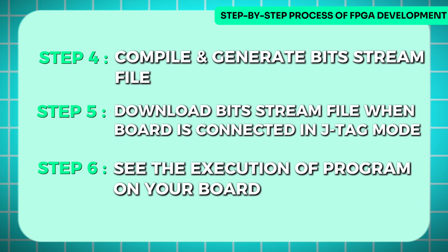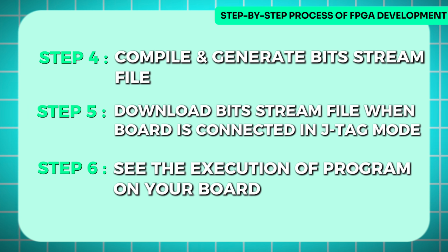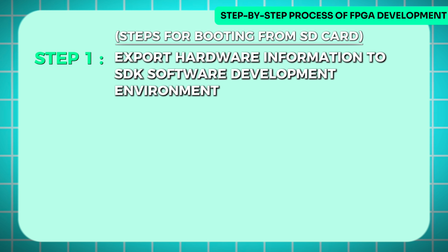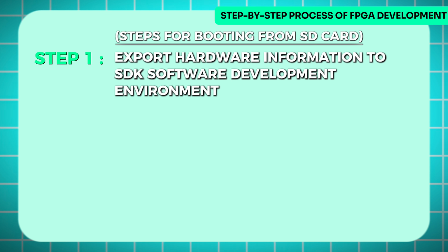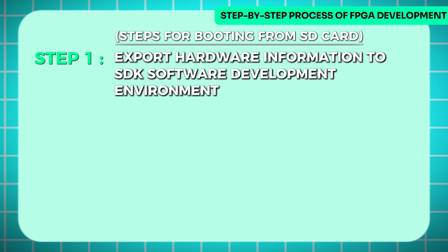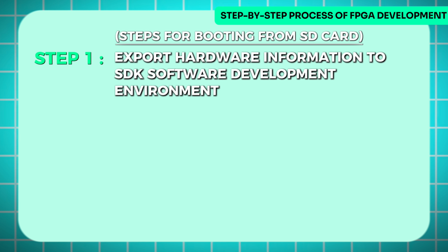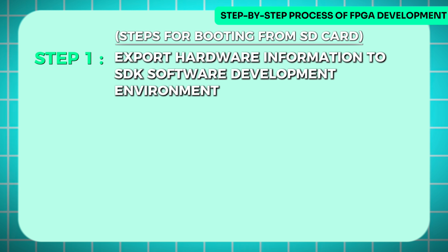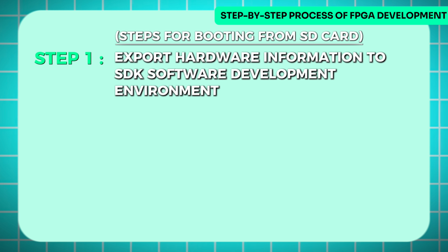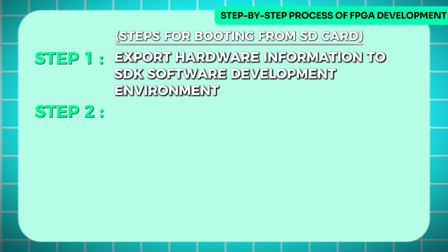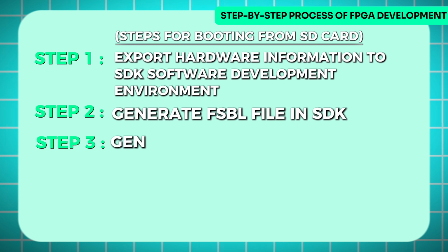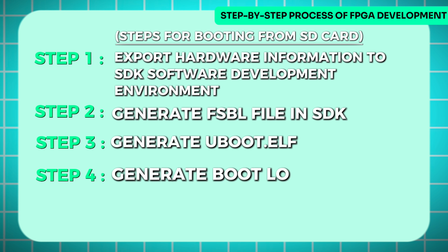Now if you want to boot from SD card, then the next step is we export the hardware information to the SDK software development environment. In the SDK environment, you can write some debugging software to verify the hardware and software combined with the bitstream file. Alright, so you can individually debug the Zynq system. Then in the next step, we generate the FSBL file in SDK. Then we generate the uboot.elf and bootloader image.